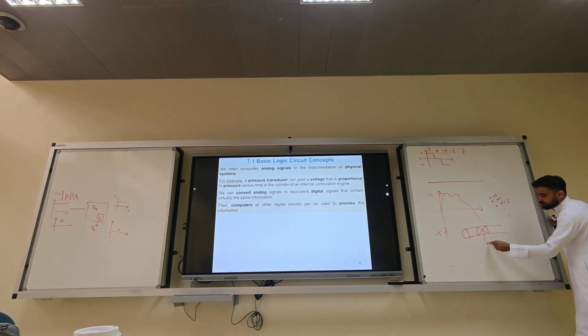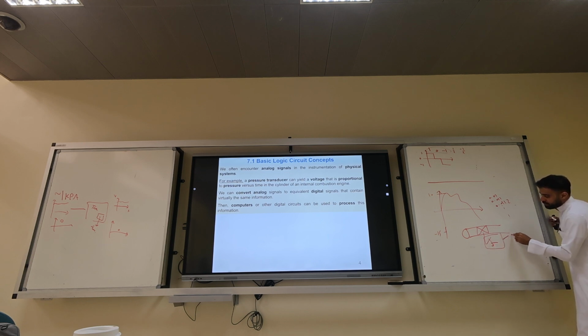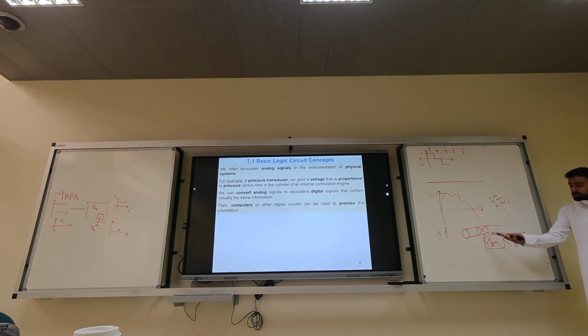The valve is either on or off, right? In the transducer most likely you will have a circuit. If there is a voltage, it gives you 1 or 0. Or plus 5 volts and maybe minus 5 volts. You don't need an analog. So a transducer also works as digital. You know the status of the valve, on or off.